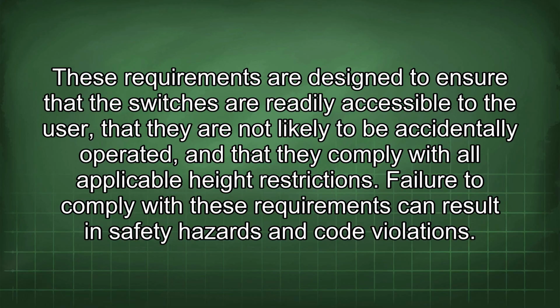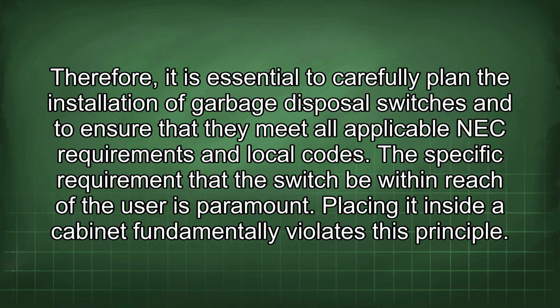Failure to comply with these requirements can result in safety hazards and code violations. Therefore, it is essential to carefully plan the installation of garbage disposal switches and to ensure that they meet all applicable NEC requirements and local codes. The specific requirement that the switch be within reach of the user is paramount. Placing it inside a cabinet fundamentally violates this principle.